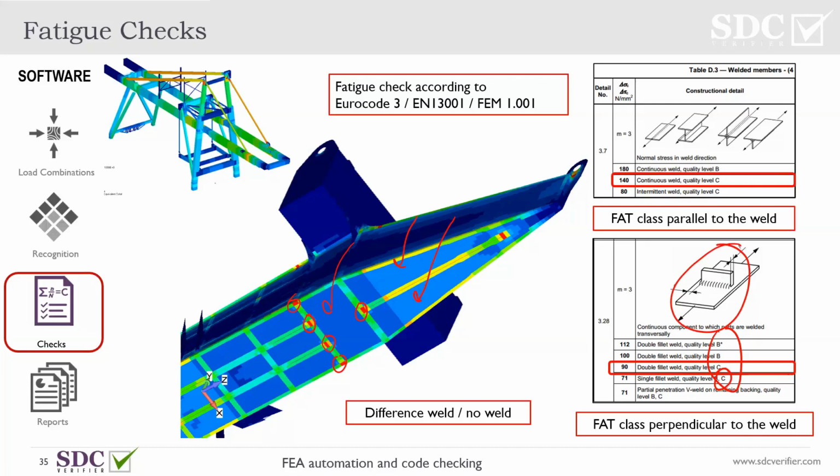Okay. Yeah, there is another one regarding notch classification, not directly related to SDC. EN 13001 notches are for nominal stress. Unfortunately, EN 13001 doesn't offer DCs for structural stress, which is what we get when modeling with shells. Design checks should therefore still be quite conservative, right?